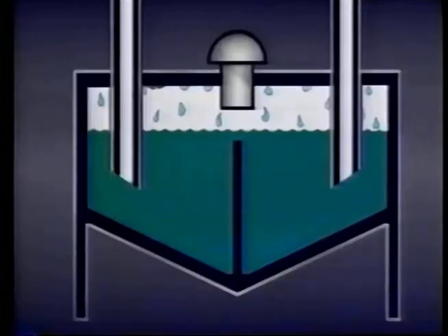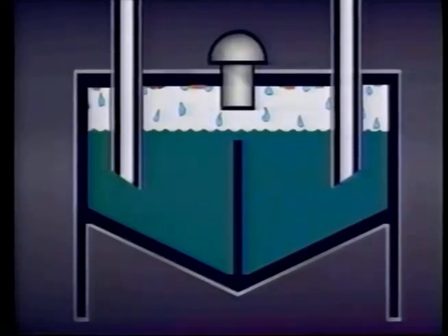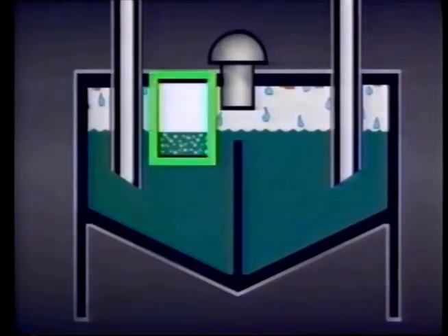Water vapor escaping from the fluid can condense on unprotected metal surfaces, causing rust. Eventually, particles of rust will flake off and contaminate the entire system. Many water-based fluids contain rust inhibitors, but over time, rust will occur anyhow. Evaporation also reduces the fire resistance of the fluid, since less water is available in the fluid.